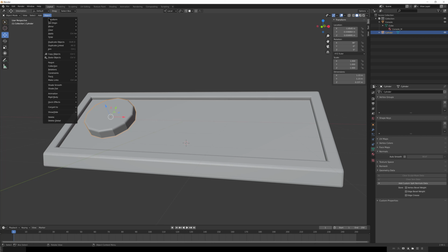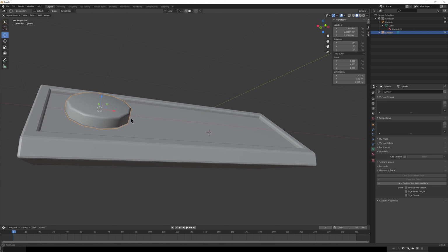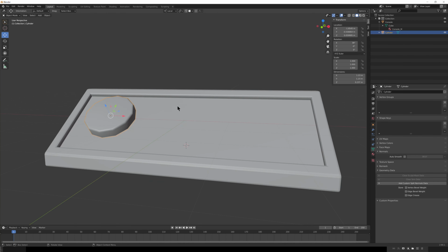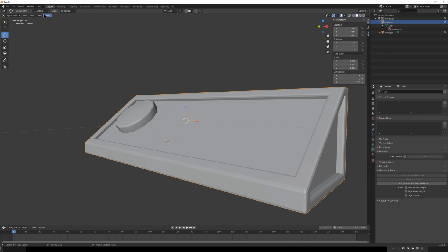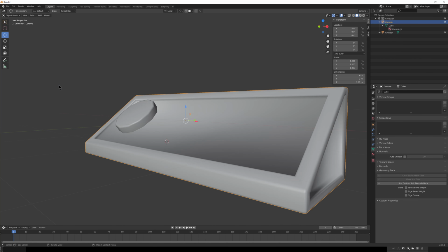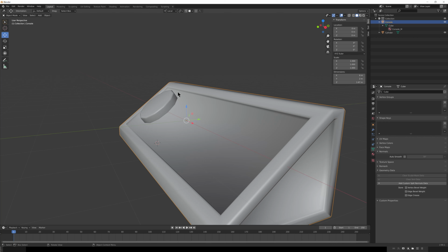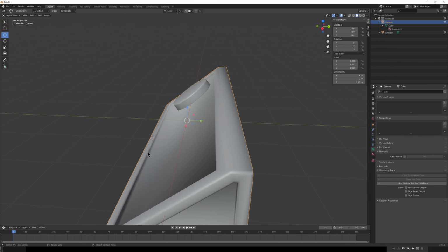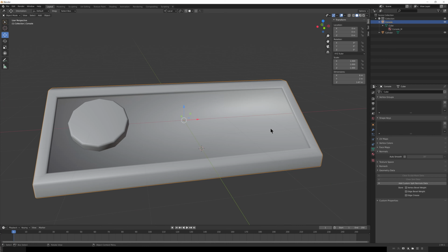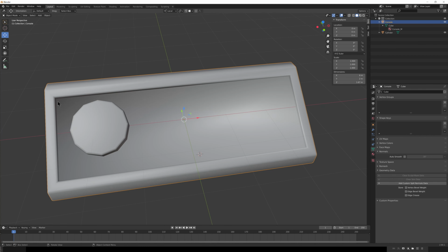Let's go ahead and go up to Object, and here you can see there's Smooth Shade and Flat Shade. If we select Smooth Shade, you can see that it's interpreting the object as smooth throughout. If we select this other object over here and also choose Smooth Shade, we're not going to quite get what we want. As you can see here, there are plenty of hard edges, and because it's trying to smooth on edges that are roughly 90 degrees, you end up with these large visual artifacts due to the fact that it's calculating light at this location and the next location, but it's averaging them together. So instead of the normal coming straight out of the surface as you would expect, it's got kind of a funny angle from being averaged with this 90-degree one over here, which causes this darkening effect.